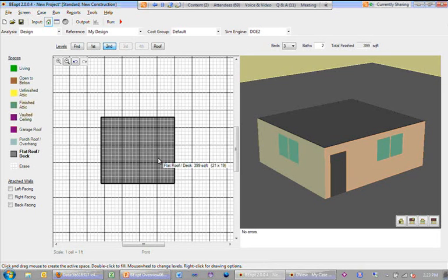Correct, because in the back shallow area, you're going to have a ceiling joist touching the roof rafter, where in the front you'll have a ceiling joist that may or may not be buried in insulation, but a lot of big airspace above it. So some of the areas will have different U values, and it will have to be proportioned.